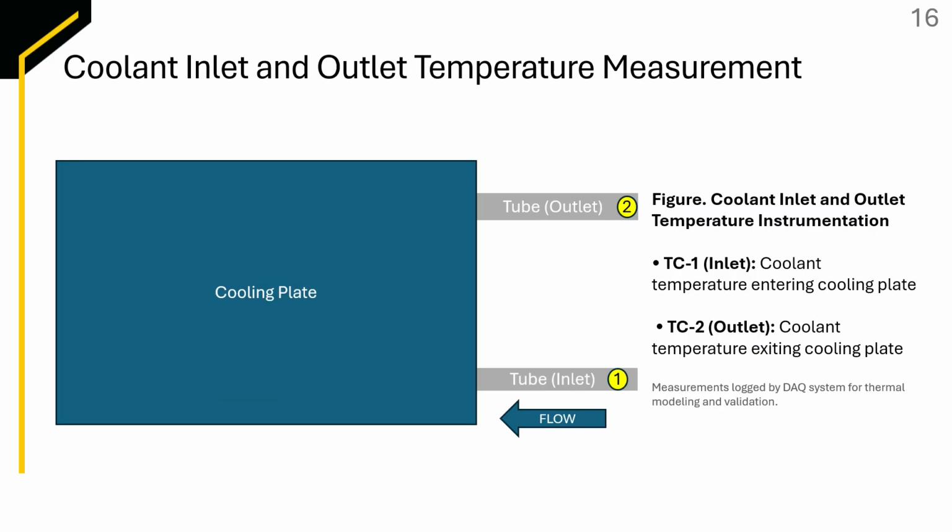For our coolant inlet and outlet temperature measurements, we're inserting a thermocouple inside the tubing, where the thermal reading is going to be taken inside the water for both the inlet and the outlet, and that is going to be fed into our DAQ system.